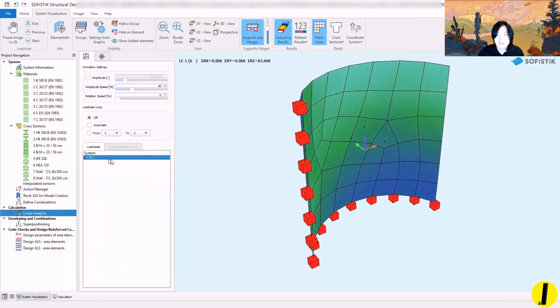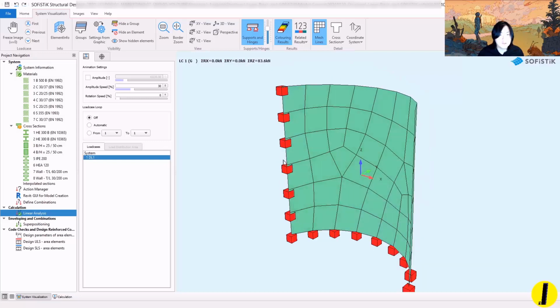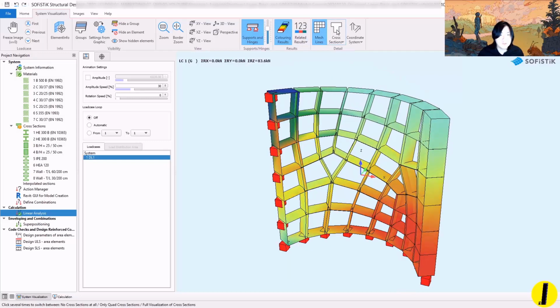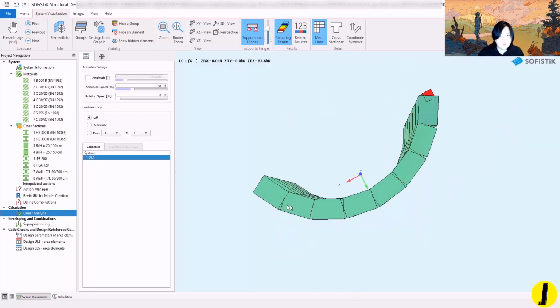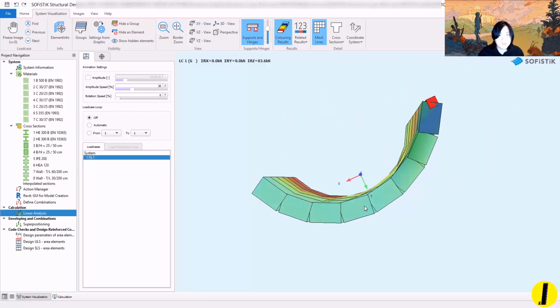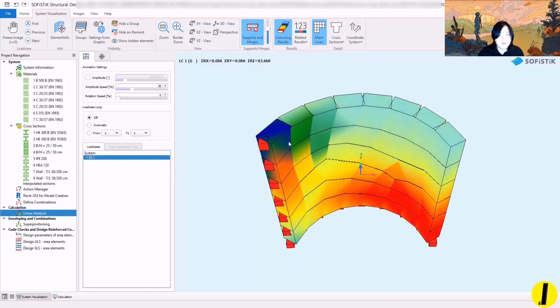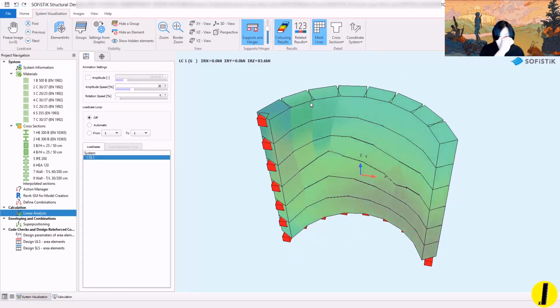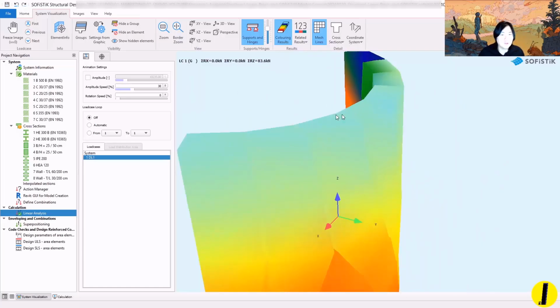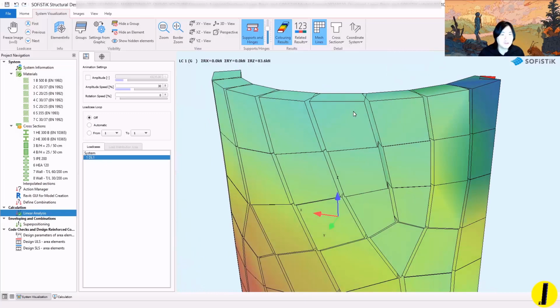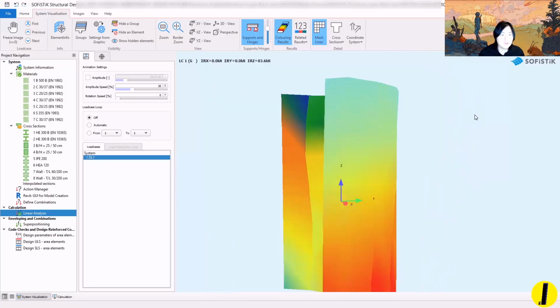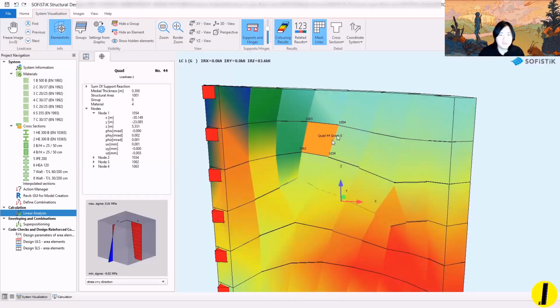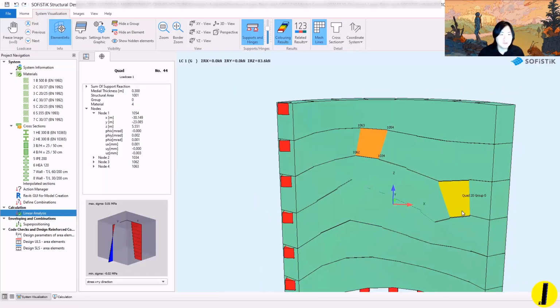Alright, the calculation is done, so you can have a look now at the deformed geometry, and I'm going to turn on the wall here. As you can see, when you have a curved wall, because it's FEA analysis, it will divide into a certain division for your chord mesh geometry, and it will get a rectangular quadrilateral mesh geometry. So this is how you can see the result.